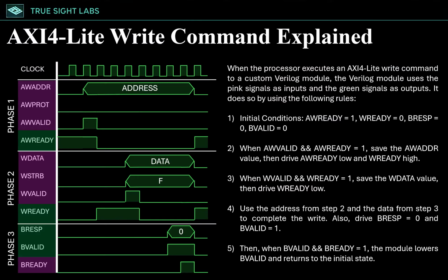So this is the summary of the AXI4-Lite write command. When the processor executes a write command, the Verilog module uses the pink signals as inputs and the green signals as outputs. The rules below summarize the entire write process. For the full explanation, watch the previous lesson on AXI4-Lite write commands.